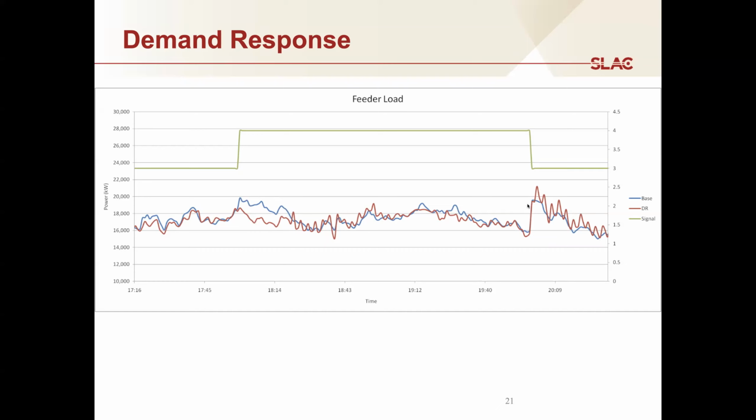But when you release the control signal, there's another transient response that looks different. And that transient response persists for some time. And if you look closely, what you're seeing here is an oscillation. And for those of you who know how thermostatic set point change demand response works, what you're seeing is essentially a whole bunch of buildings behaving in concert with each other for a time before eventually that itself decays.